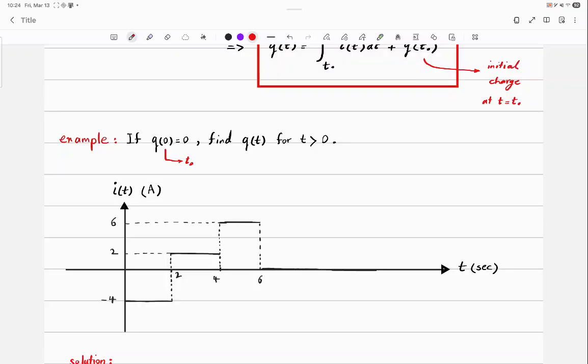That is the basic idea behind this. If the current enters from the positive terminal of the voltage and passes through the element, energy is absorbed by the element. If the current enters from the negative terminal and leaves from the positive terminal, then energy is supplied by the element. From the way I'm representing this in your lecture note, you should guess that this is pretty important, okay?